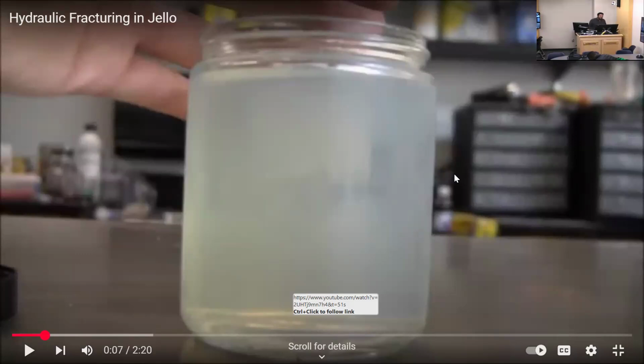Now, what this lady is gonna do, she has what resembles a reservoir, a jar full of solidified gelatin. She's gonna go in with a straw and try to inject a juice or something. She's gonna do it at a shallow depth where the overburden is not higher than the confining horizontal stresses, and the fracture that she's gonna get is a flat, pancake-like fracture. This is because the fracture opens by doing work against the smallest of the stresses. In that case, it's the overburden. So the thickness of the fracture would be parallel to the overburden stress. So it's a pancake-like fracture.